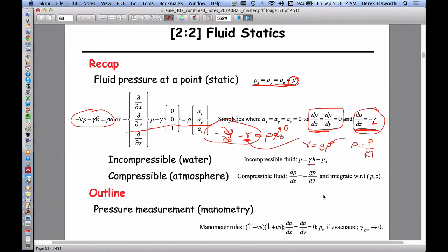The reason that you get a portion of a storm surge, I guess this is turning out to be longer than I thought, is that if you think about the surface of the sea, which is usually horizontal, and you had a pressure in the center which was lower, then you'd expect this lower pressure here, PC, would physically suck up the water.